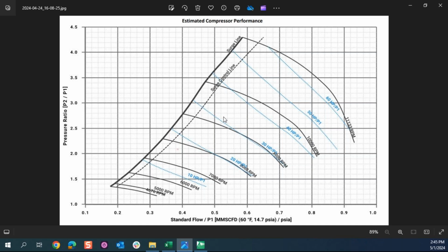From our sizing scenarios, we know that the compressor map is going to want to try to find a compression ratio of either 2 or 3. I'll talk about the 2 right now. So it's going to try to find some sort of solution kind of on this line. And the only thing that's actually bounding it is the curve that we're going to specify RPMs for. So we might try to specify something like this. And what we want it to find is this point here, where those two are lining up.